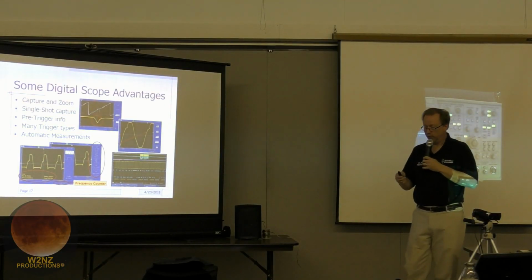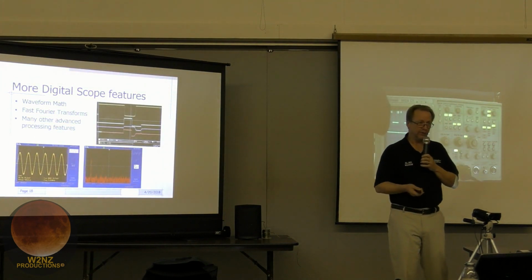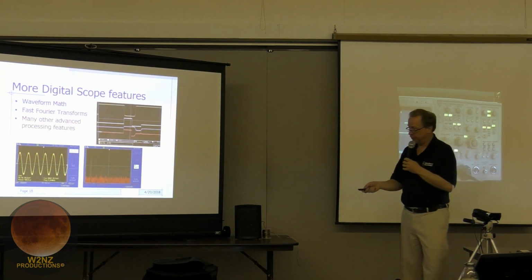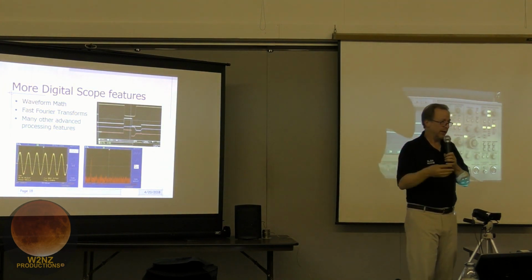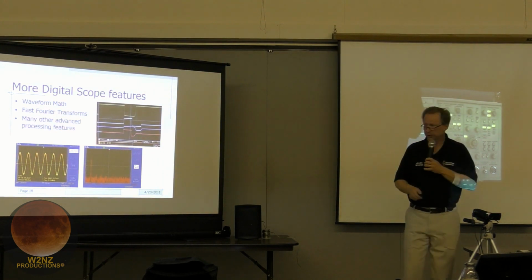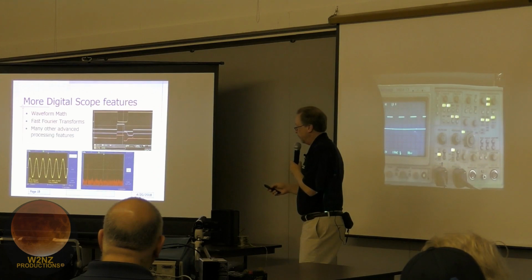Even doing things like Fourier transforms to give you the spectral content of the signal coming in. You get almost spectrum analyzer functionality by just doing math on that input waveform. So you can do all different types of math on waveforms.